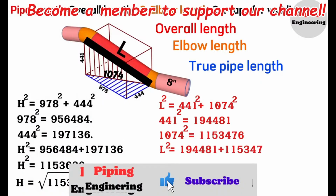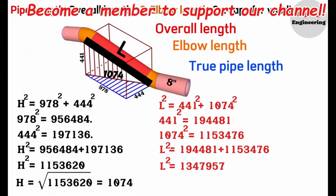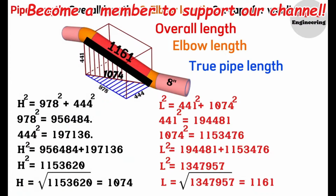So, we continue to calculate that L squared will equal 194,481 plus 1,153,476. Using the calculator again, 194,481 plus 1,153,476 will equal 1,347,957. So, we find that L squared equals 1,347,957. Again, using a calculator, L will equal the square root of 1,347,957, which is approximately 1161. The hypotenuse of the vertical right triangle also serves as the overall length, or the center-to-center distance between the two elbows.